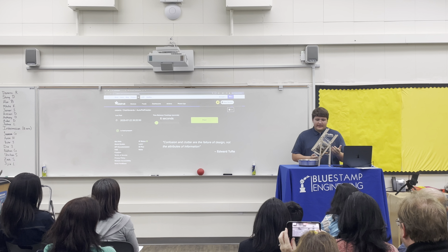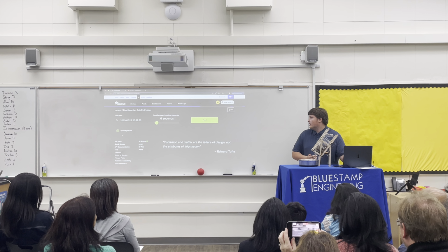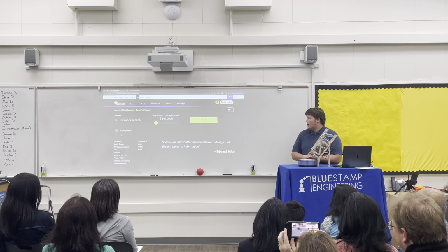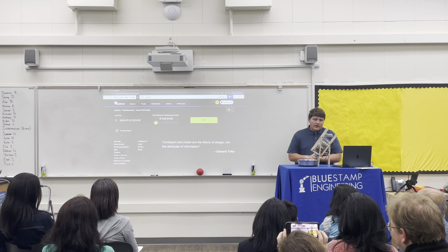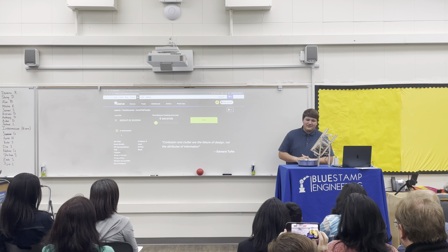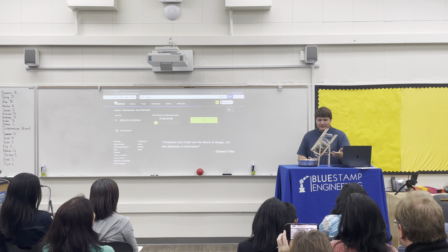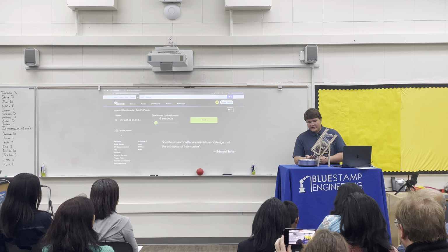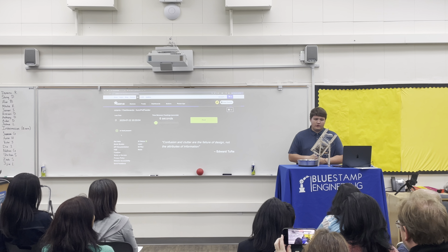So first, the Wi-Fi connection allows me to use this website, adafruit.io, which allows me to hook everything up. Secondly, the more efficient part was actually less efficient in my case, as I had to hook up my servo to batteries, as the servo takes a different voltage than the ESP32 outputs, unlike my Arduino.